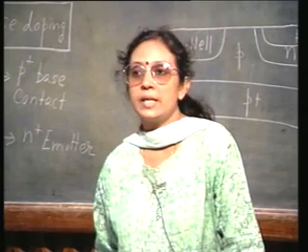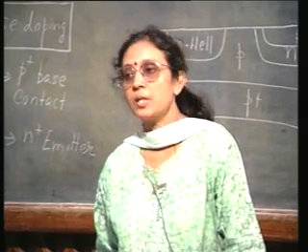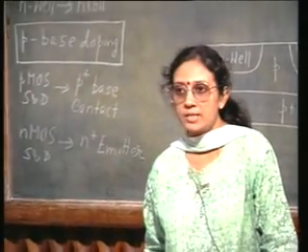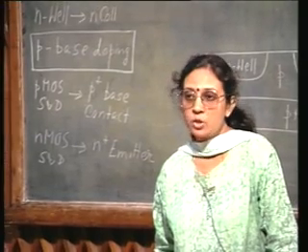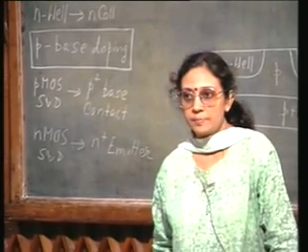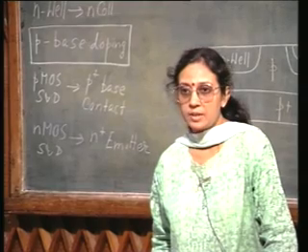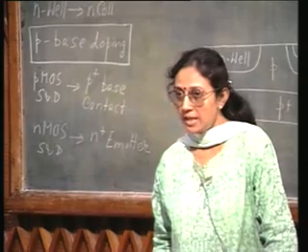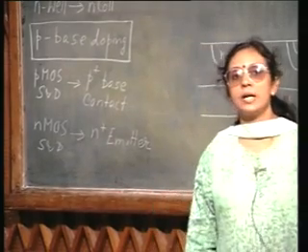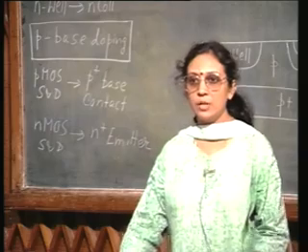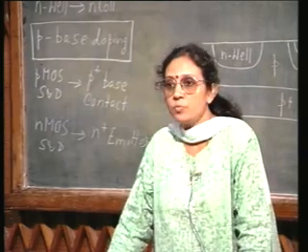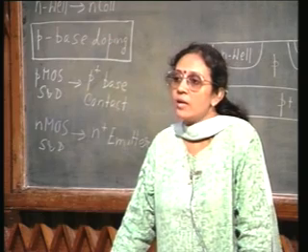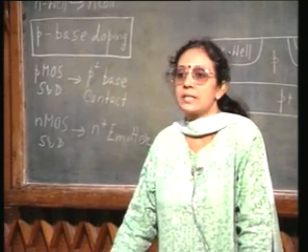Okay. Now, if we look at the basic requirements for an NPN transistor, we see that we have needed only one extra step, the step in the box, that is the controlled intrinsic base doping, for which we need a low Gummel number, right. The total charge in the base region must be fairly low, so that the beta of the transistor is kept high, and this doping has to be carried out separately. We cannot use any common step with CMOS. So, essentially you have needed only one extra step,